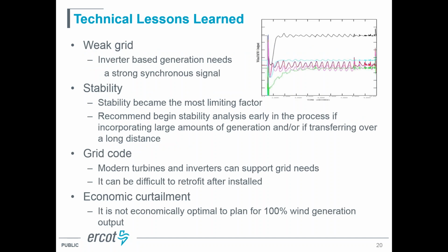So I wanted to share some lessons learned, and I'll start with technical lessons learned. And the first is this idea of a weak grid, and that term I know is kind of offensive to some people, but I think that's the term the industry uses. It's this idea that these inverter-based generators, such as wind turbines or even solar inverters, the technology today is such that they really need a strong synchronous signal.